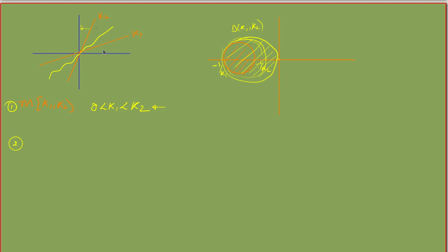Now let us try to push this K1 down and see what happens, to what maximum we can push it. As we go on increasing K1, what happens to the system? Let me put minus 1 by K2 over here itself, because here or here it doesn't matter. What happens if I try to push K1 downwards? When K1 decreases, minus 1 by K1 is pushed to this line. The curve goes on increasing. The initial curve was something like this. This was the forbidden region initially.